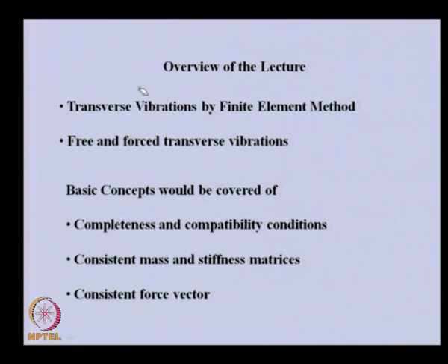Basically, we will be covering the transverse vibration using finite element method. Both free and forced vibration we will be considering, and similar to the torsional vibration case, various concepts of finite element method like completeness, compatibility conditions, and consistent mass and stiffness matrices we will be deriving. We will even be deriving the consistent force vector.